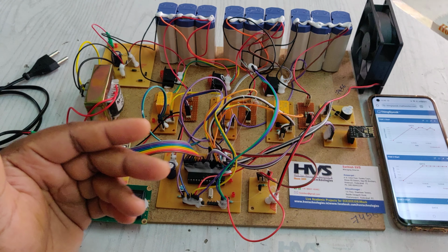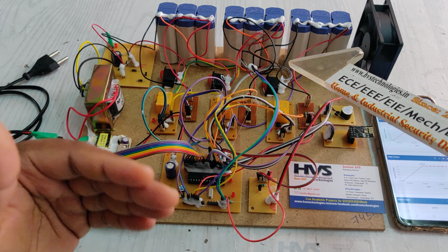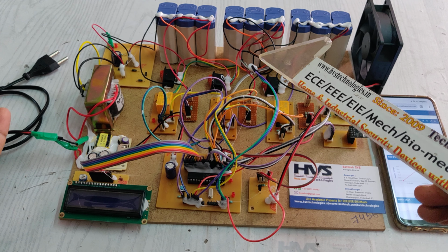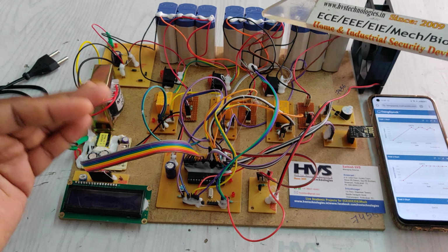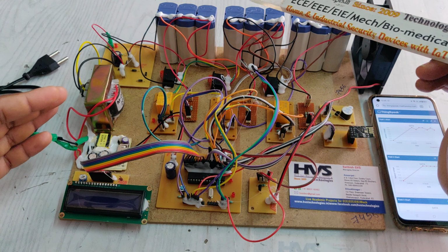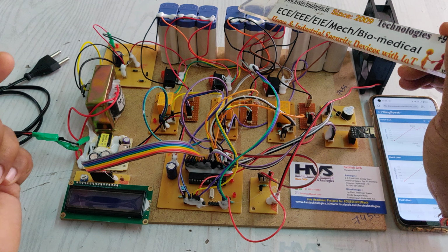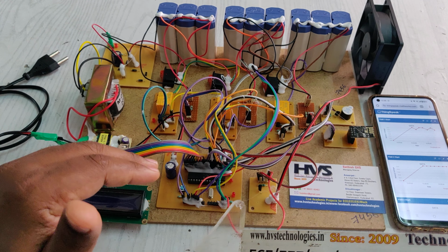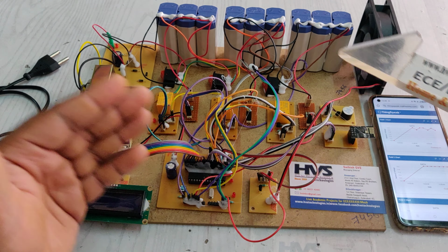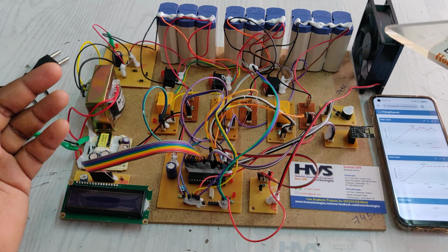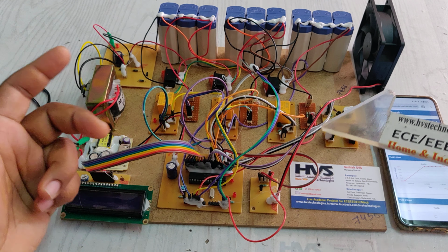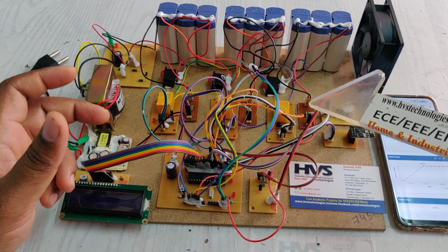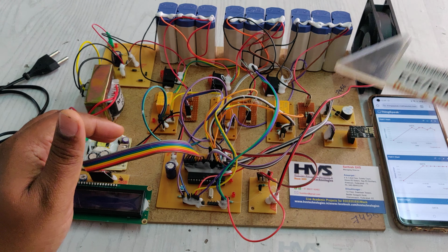And coming to passive cell balancing, it will reduce the voltage by adding a load to the excess voltage to reduce it to the equal voltage of the lesser voltage battery pack. For example, in passive cell balancing, if it is 10 volts and this is 11 volts, then by adding a load to the respective battery pack the voltage is reduced to 10 volts. So reduction of voltage is passive cell balancing, and transferring voltage between the battery packs is called active cell balancing. This is the main concept to maintain the battery life in electrical vehicles for maximum lifetime, and that will be achieved by our microcontroller.